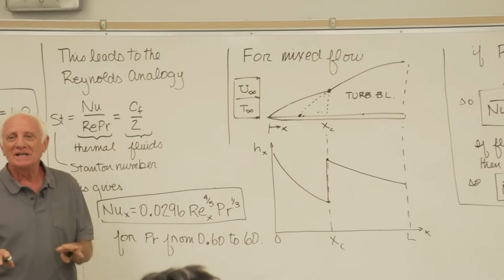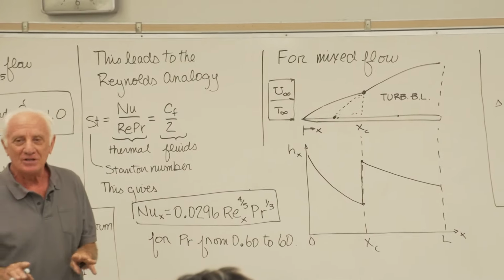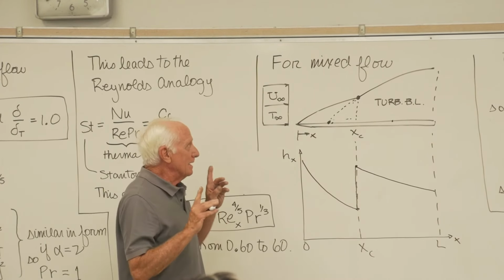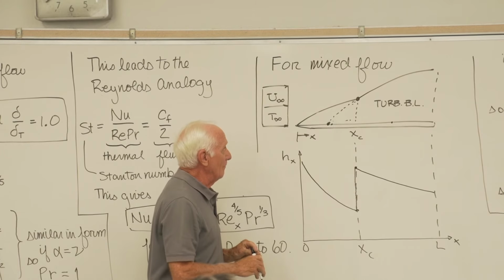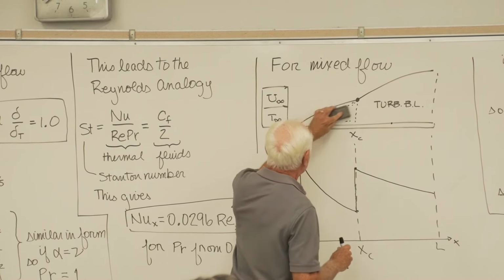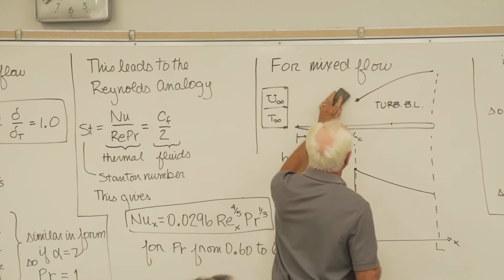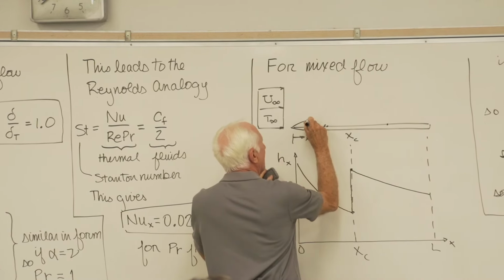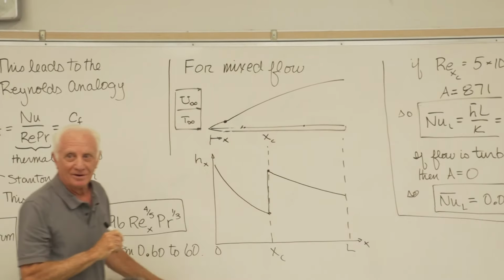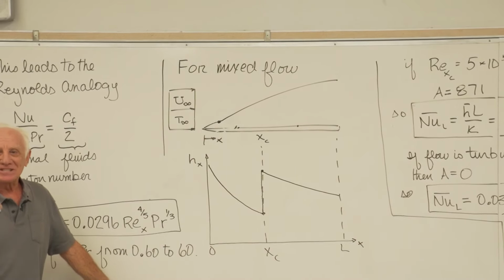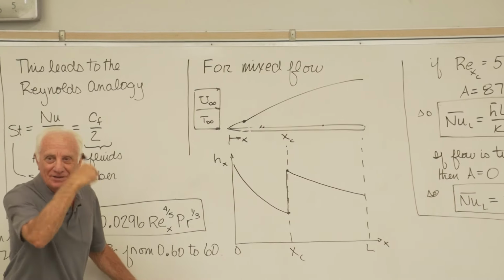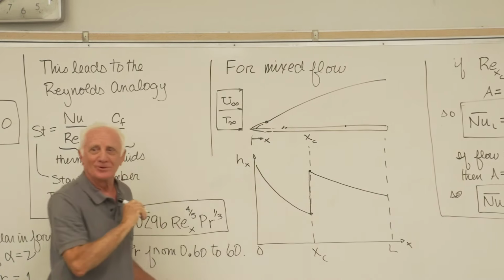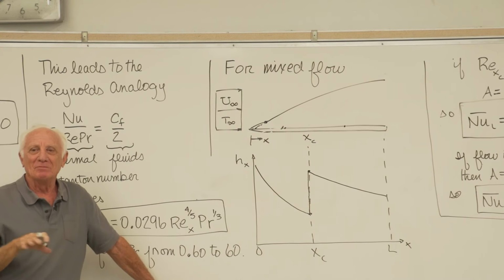But the textbook doesn't want to get that involved. You can do it that way. You've got to work backwards. But it's much more complex. And typically, here's why it doesn't matter too much. For most flow situations, here's what happens. There's laminar, there's turbulent. Now extend that turbulent boundary layer back to the plate. Ooh, it gets real close to there. So the error becomes minimal.